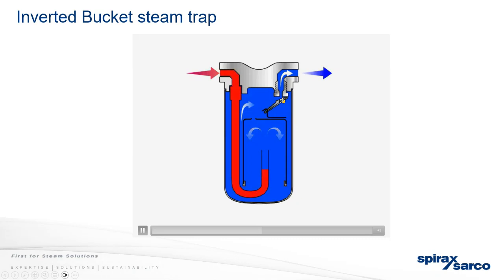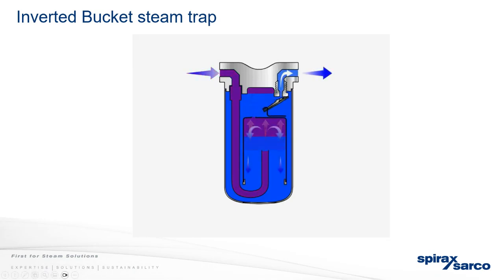And then you have steam, hot condensate coming in, which fills up. As it flashes off, it produces gas under the bucket, fills the void at the top, and slowly starts closing the trap. So the air hole, if I just go back to my pointer, is here. And as you can see, that's how it escapes and fills the area up here.